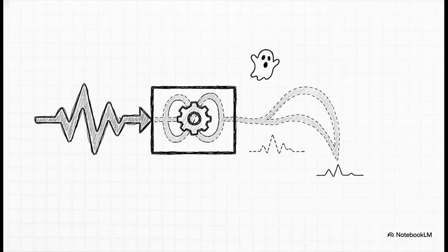When two or more strong signals pass through a nonlinear circuit element in your radio, like a mixer, they don't just pass through cleanly side by side. They actually interact and modulate each other. As these signals mix in a nonlinear environment, they spawn new frequencies. This generates entirely new, undesired intermodulation products right out of thin air.